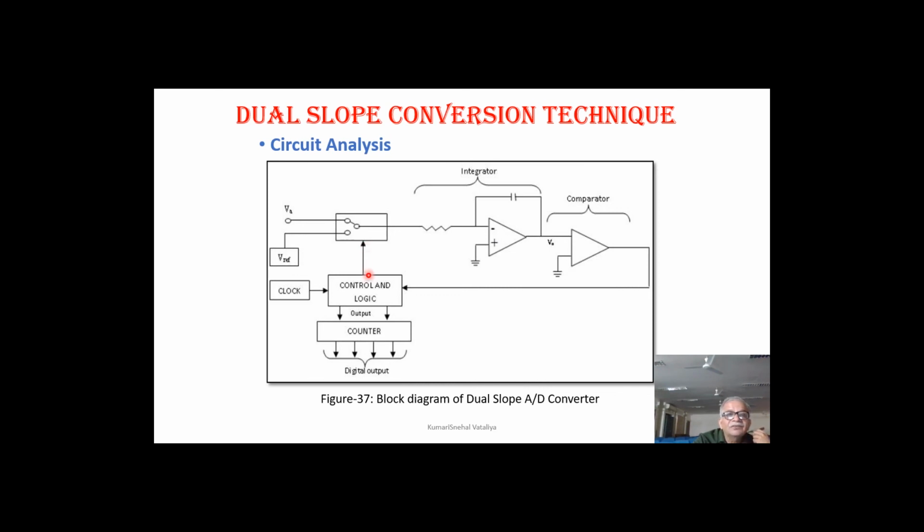Now this DAC circuit, dual slope, that RC integrating circuit is here, and that will produce a reference voltage. Now the reference voltage is negative to this polarity. So we are cancelling this R and C in this process. This integrator component R and C will be cancelled, and your output voltage will be independent of R and C components. So these will cancel as constants, and therefore even if you replace the capacitors or resistors, or because of temperature, pressure variations, if there are changes in the components, it will not affect the error.